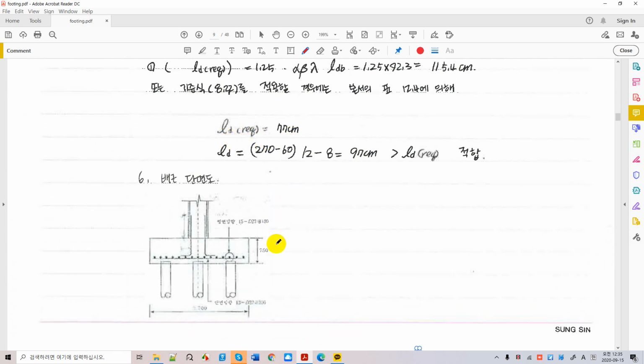So you're okay. This is probably your design details and construction document, and people will construct based upon your construction document as shown there. We have 3 piles, and we have rebars placed differently in both directions because your pile arrangement is not symmetrical anymore, and we have the development length checked already, right? It's beautiful, right? And we see how to design the splice length from dowel to column rebars. The same theory applies here between columns and pile caps, and everything's under control, right?